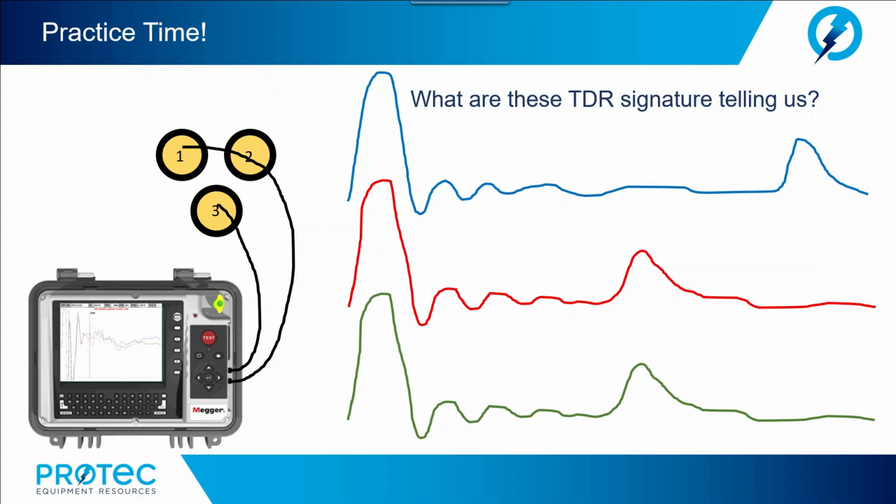Finally, we now connect between conductor 3 and conductor 1, and we capture the following pattern. What is the nature of the fault that we can conclude from these 3 captured traces? Take a moment and enter your answer into the question function.